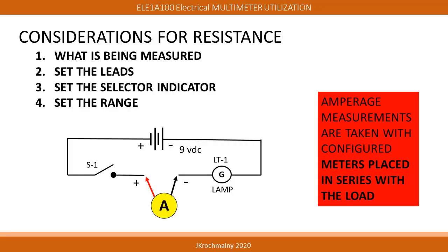Once configured for the amperage measurement, the meter is placed into the circuit in series with the load. Notice in this graphic, the power has to be supplied to the circuit in order for the meter to read its amperage value.